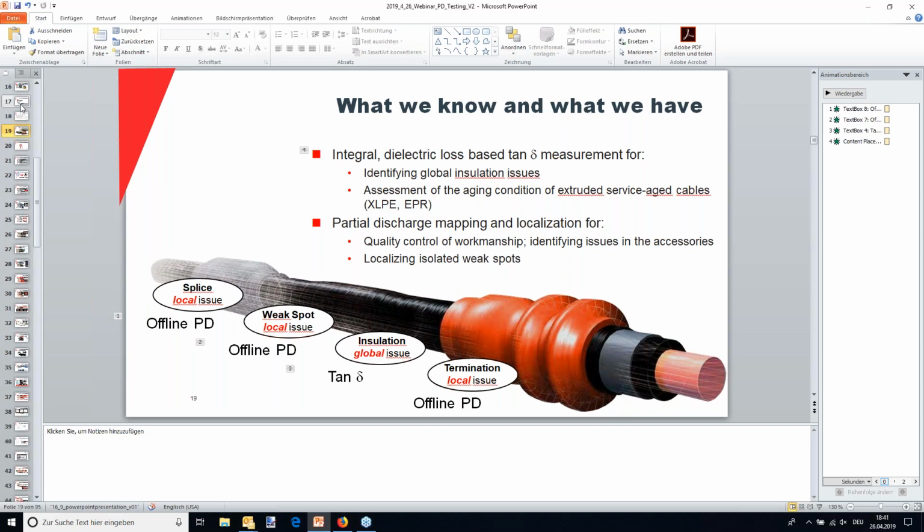Right, well, excellent. Next question is, what is your take on MV cable rejuvenation? Does it really work as a long-term fix, or am I buying a few months when the cable replacement is really needed? Okay, so I assume that you had some visit from our friends from Novinium. Novinium is doing, for instance, these cable injections. And you have to say, from a chemical point of view, it works to a certain extent. The problem with solid dielectric cable is that when you change the dielectric properties, you see big changes in what you measure during the condition-based testing.